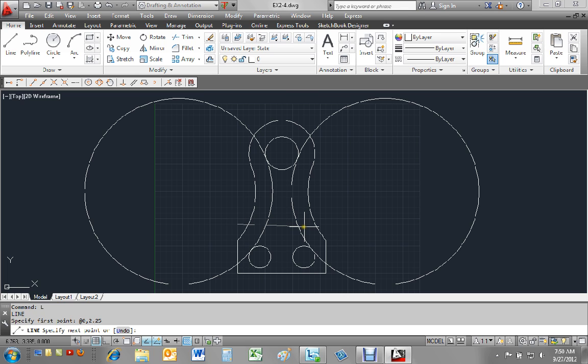Alright, I'm going to turn on my ortho command, toggle, by pressing F8, and just draw it out here at an arbitrary length. Free input. Just pick. Alright. Now we do a trim. I'll use this as my trim cutting edge, and this is my cutting edge. And I'm going to trim in a counterclockwise direction.